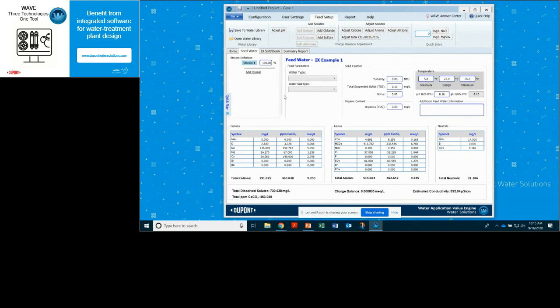So in this case, just for the sake of example, I might take the design temperature and drop it to that minimum, or, and that's what I think we should do here, but another way to do it might be to bring that design temperature a little closer to the minimum so that you're not going to exceed whatever threshold you have set for yourself. But if we want to just step forward by setting that design temperature at 5, then we can do the same thing in terms of evaluating our design at different temperatures once we get to the summary report.